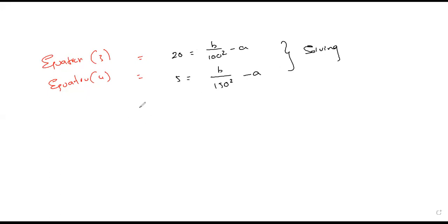A value, B value? A is 7, sir. Very good. B? B is 2,70,000. Correct? Yes, sir. These are just mathematical equations. I think you can do this straight away in your calculators also, right? Yes, sir, the calculator has a direct option. So these two are constants. This is how you can calculate your constants. So substitute your constants in the Lame equations.